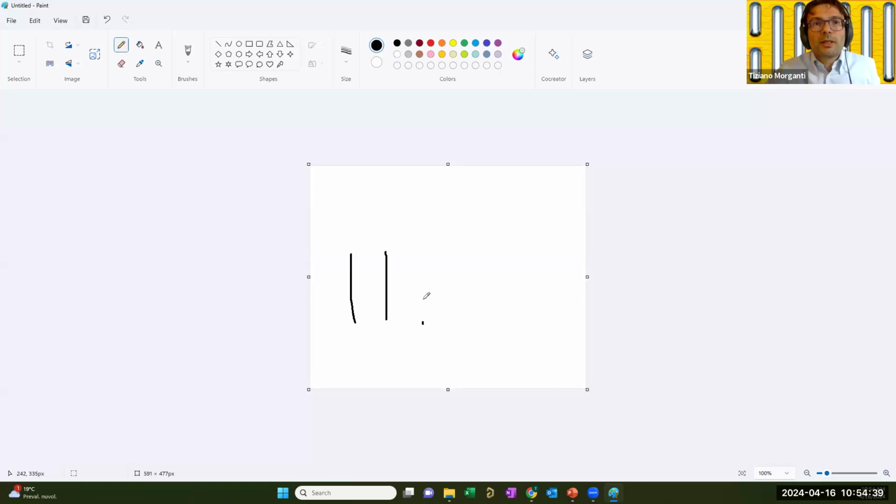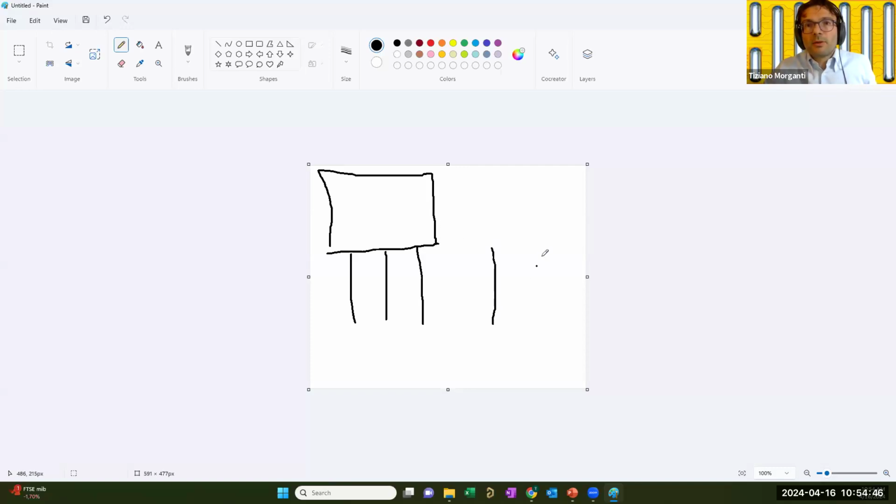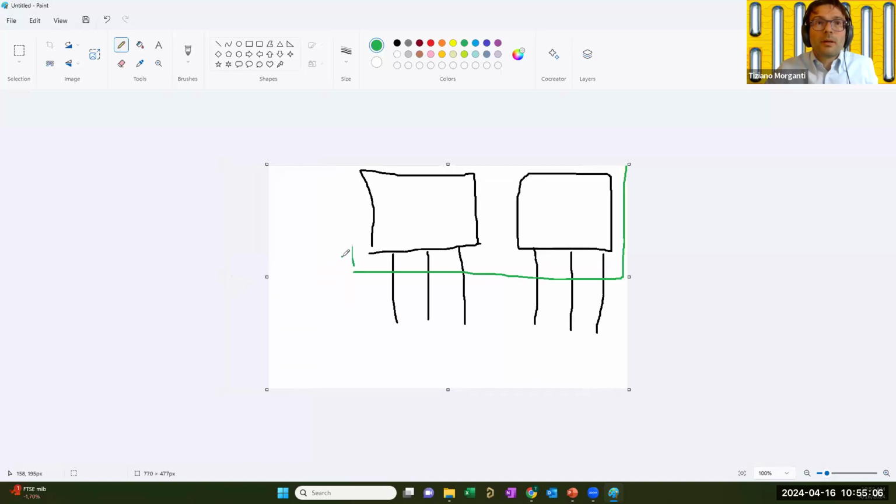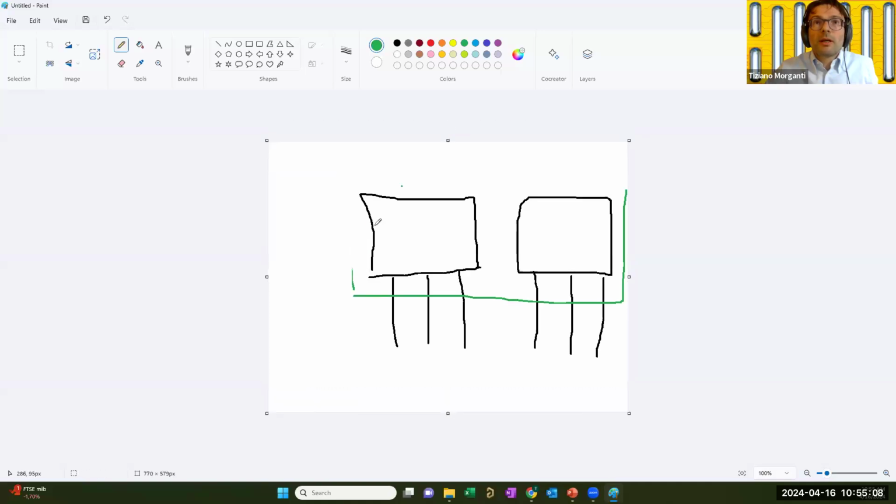So you have the TO220. So you have the other TO220 of the half bridge. And inside there is the EPC GaN. So this needs to be a single PCB. Okay. You need to have the bypass capacitors on this PCB somewhere here.